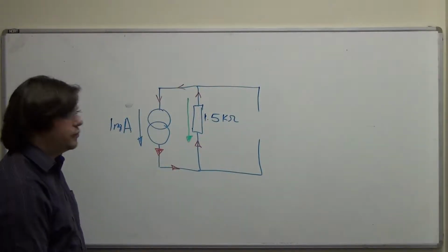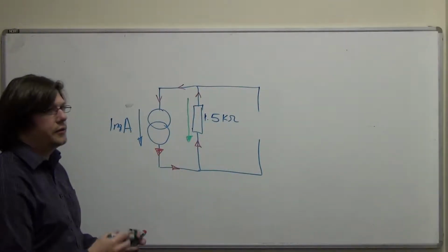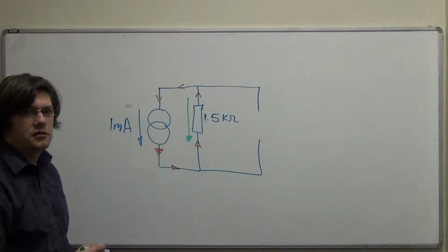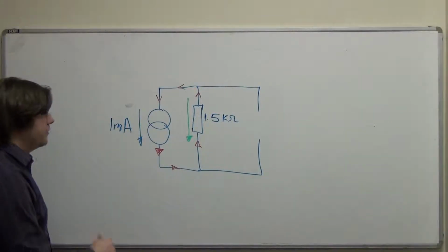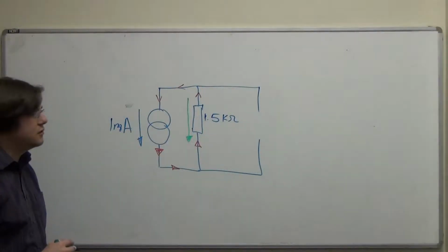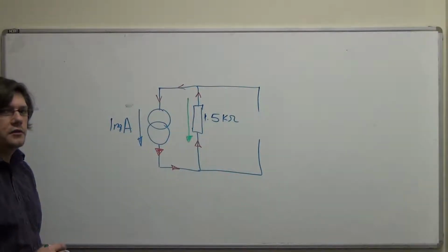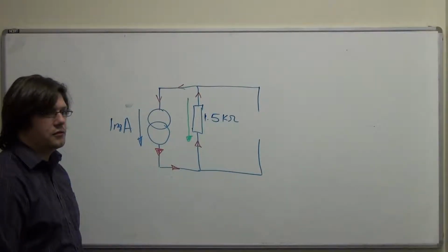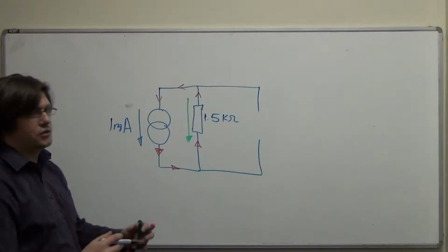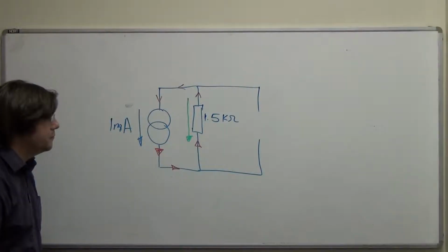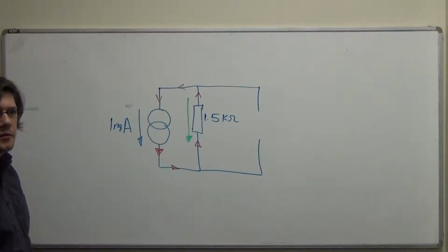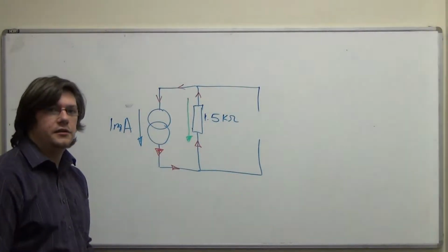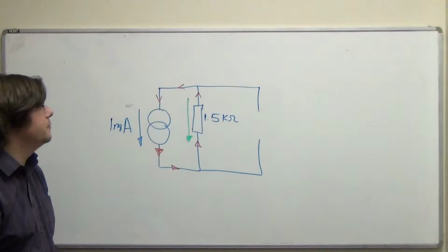If I don't, I've broken some laws, and what I'd be saying in that breaking of laws is that the resistor is giving energy to the circuit, and that isn't the case. Sources have their current and voltage in the same direction. Dissipators don't. Resistors are dissipators, and voltage and current sources are sources. And you can have a source of power as well if you wished. Perfect inductors and perfect capacitors do not dissipate any power, although real inductors and real capacitors do dissipate power.